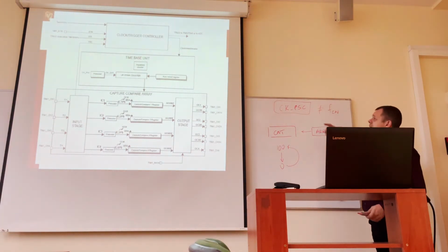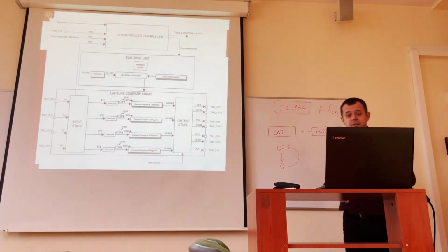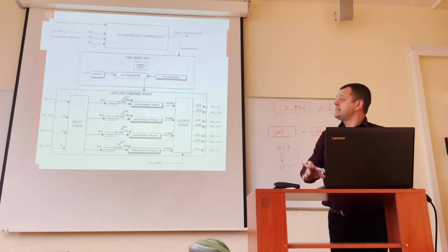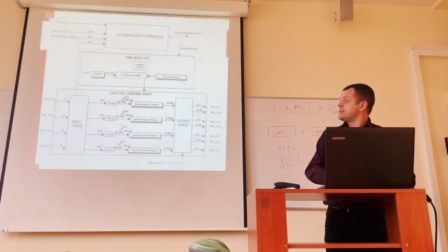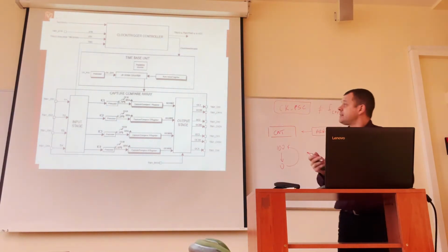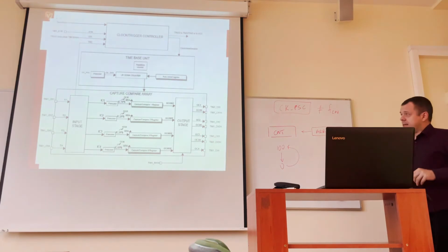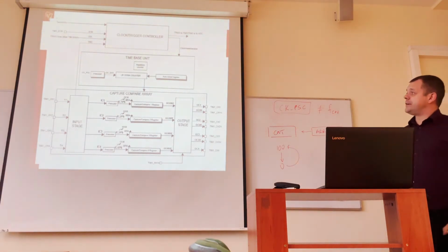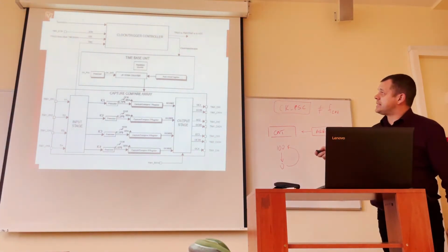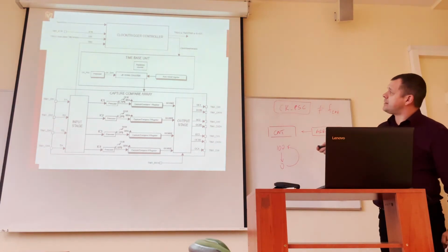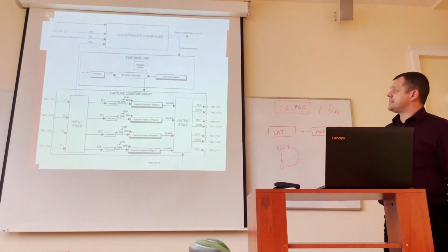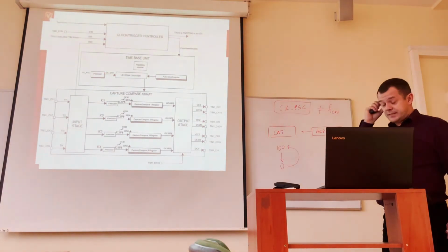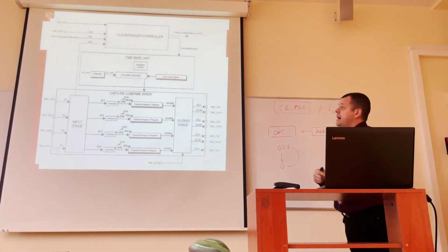Sometimes we can make it even, but quite often the timers are clocked at a different clocking, and finding how it is clocked sometimes requires an analysis. It's not always that readable, to be honest, and sometimes even I lose a few minutes to find the frequency that is the input to the prescaler. Of course, depending on the setting of the prescaler, the counted signal CK_CNT may be different. This is important.